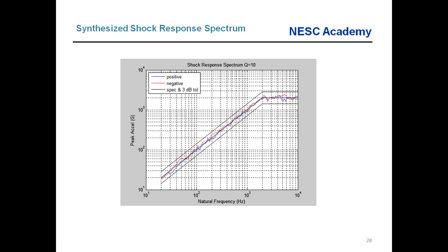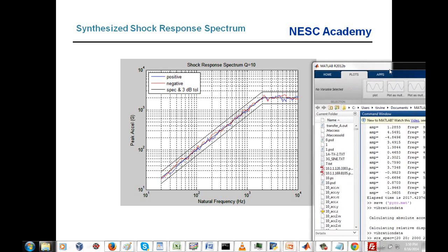And we're sort of assuming here that the natural frequency of our structure is going to be 40 hertz or higher. Now, we could take the SRS of our signal and see what it is below 10 hertz, and we'd probably see that it starts to fall off at maybe about 12 dB per octave. So there is energy down there in terms of response anyways. There would be response energy below 20 hertz. But for 40 hertz or higher, we're good to go with this.